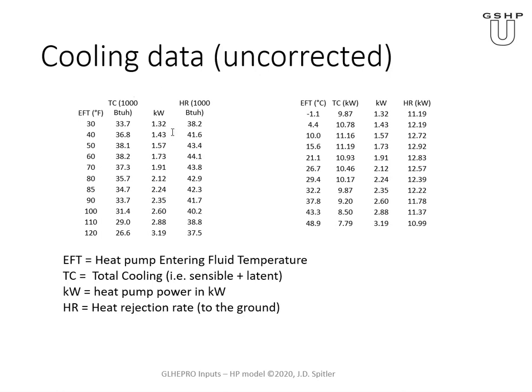The heat pump power here is in kilowatts. If you're from somewhere where they use SI units and you're wondering why we use BTUs per hour here and kilowatts here, it's because we pay for electricity by the kilowatt hour.